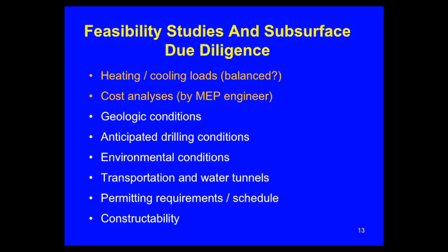So I'll give two obvious examples. If I want to put a geothermal system in to cool a hotel in South Florida, forget about it. That's all I'll be doing, trying to cool. I'm never really going to try to heat a hotel in South Florida. And all I'll be doing is rejecting heat into the ground. And after a while, instead of the average ground temperature beneath my hotel in South Florida being 72 degrees, which is the average temperature, and it's still pretty good to reject heat when you have 90 degrees out, eventually all I'm going to do is take that ground and heat it up. So it's not going to work in South Florida.